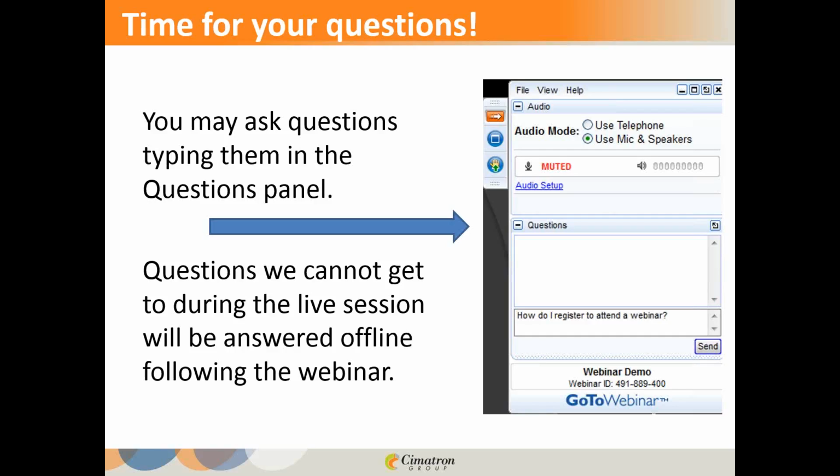Well, in that case, it'll show you what's going to happen, and you can take this information back to the customer and say, look, we know with our experience and what we're seeing, you can't form the part the way you've got it designed. You have to allow some considerations in these key areas, such as the radiuses. It is what it is at that point. The material is going to act like the material. So you can make adjustments to the gauge thickness, the material type, all that, but that's the kind of thing you have to really go back to your customer on to get his approval anyway.